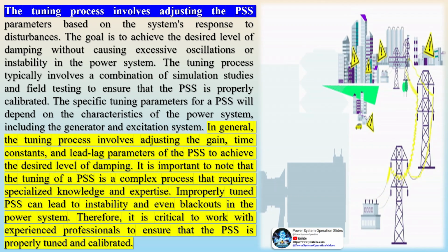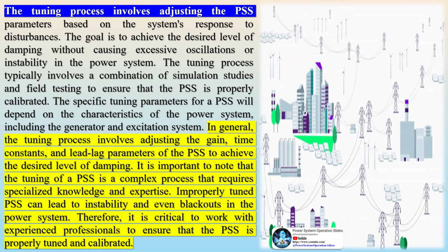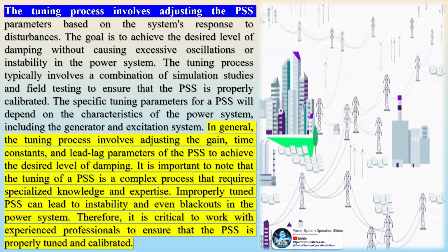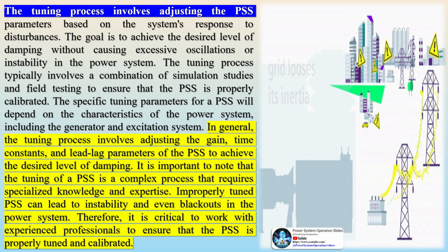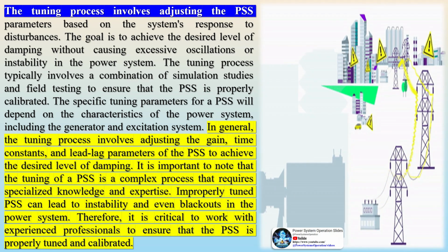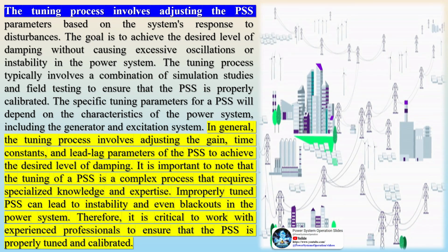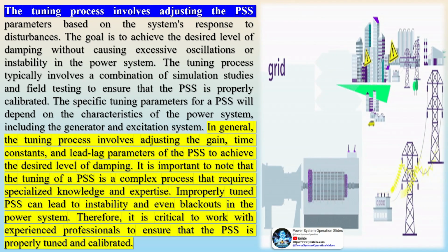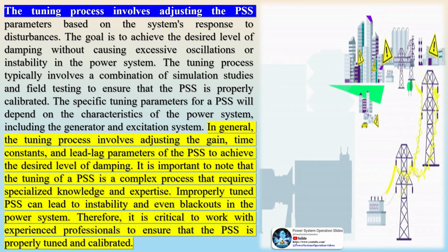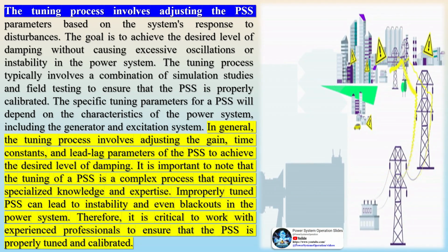Step 4, PSS gain selection. The modal analysis is iteratively run for increasing values of PSS gain K until the damping ratio of the dominant mode is at least 15%, the selected value being 24 pu. The time domain response of the system to a step change in the AVR reference signal is simulated and compared with the response without PSS from step 1 in the same plots.